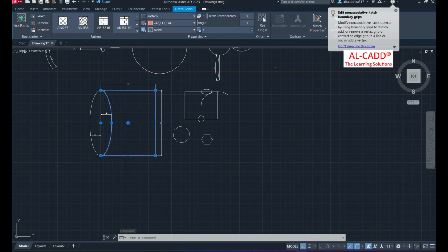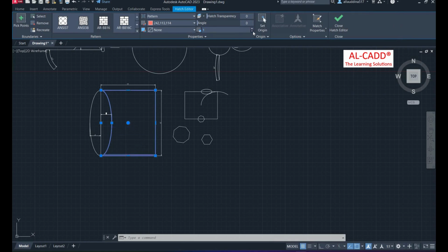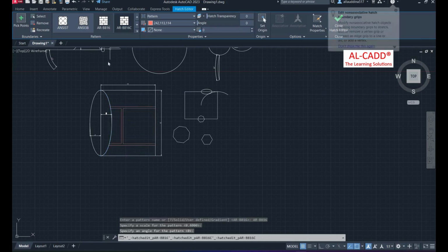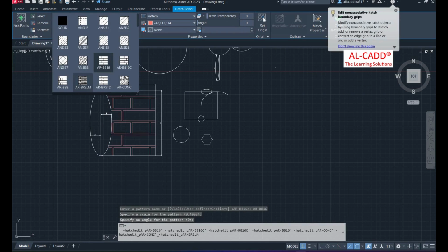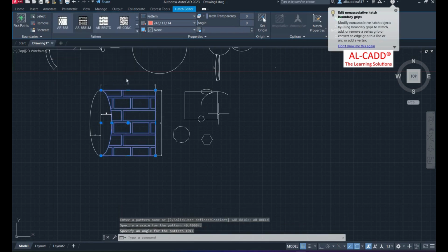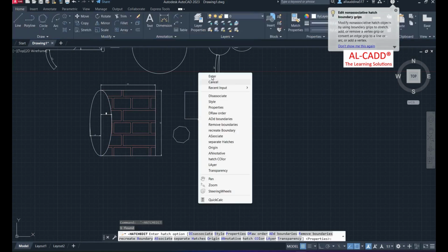If I take this hatching or the 0.5 hatching, you can apply the hatching based on the particular value. See, if I reduce this hatching, now it's showing this hatching again. So if you don't require this hatching, and you require another type of hatching, then you can just select the remaining types of hatching. So this can be done in the hatching category.